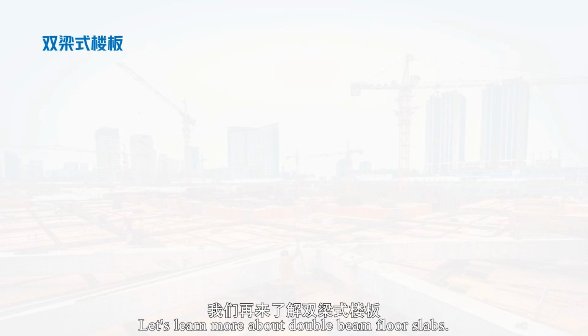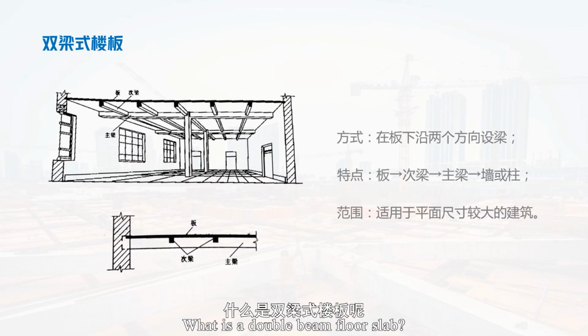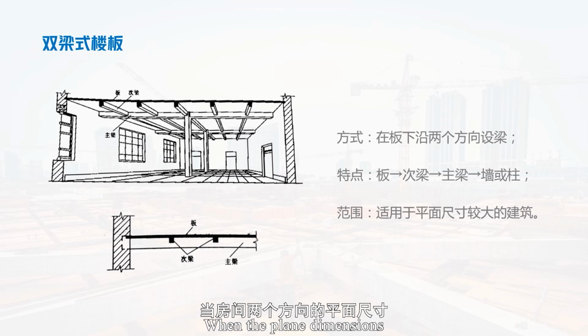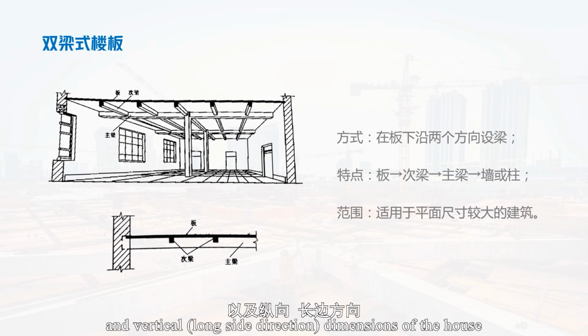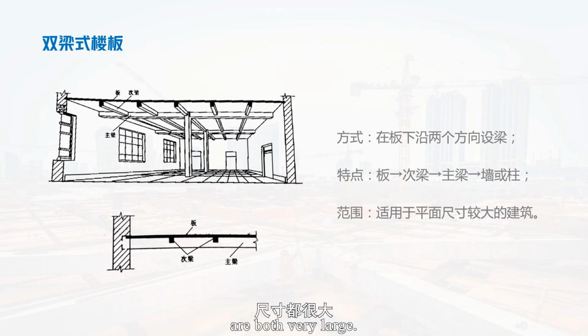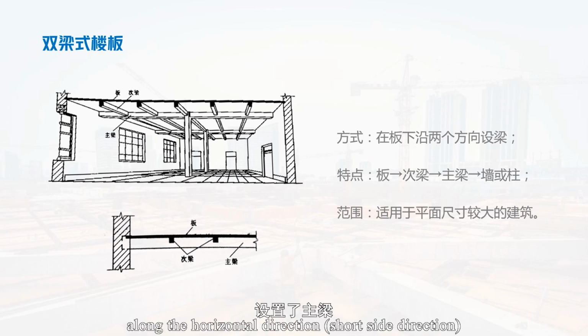Let's learn more about double beam floor slabs. What is a double beam floor slab? When the plane dimensions in both directions of the room are large, we need to set beams along both directions below the board. From the picture, we can see the horizontal short side direction and vertical long side direction dimensions of the house are both very large. So, we set the main beam along the horizontal direction, short side direction, and the secondary beam along the vertical direction, long side direction.